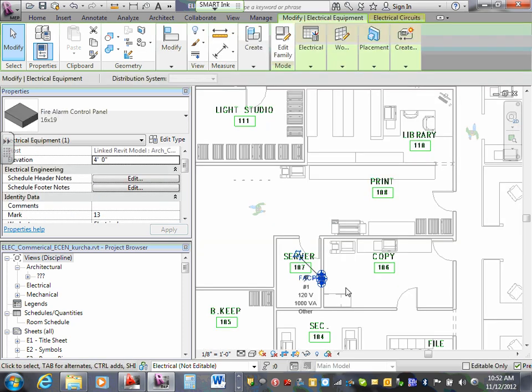Any comments, guys? Any questions? What we did, my friends, is, I'll be with you in a second. We have E7 to lay out all the low voltage equipment: fire alarm, security, point and data. No circuiting at all, except for the panel from the power lighting panel, security circuit. Then we have the riser. You have two options: draft in Revit, or draft in CAD and import to Revit. Either or. And that's it. That's the low voltage stuff. Any comments, guys? Any questions? That's enough to get you kicking.